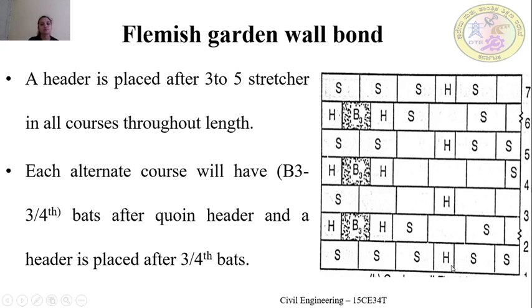So in each course both stretcher and header will come, but a header will be placed in each course only after placing 3 stretchers.